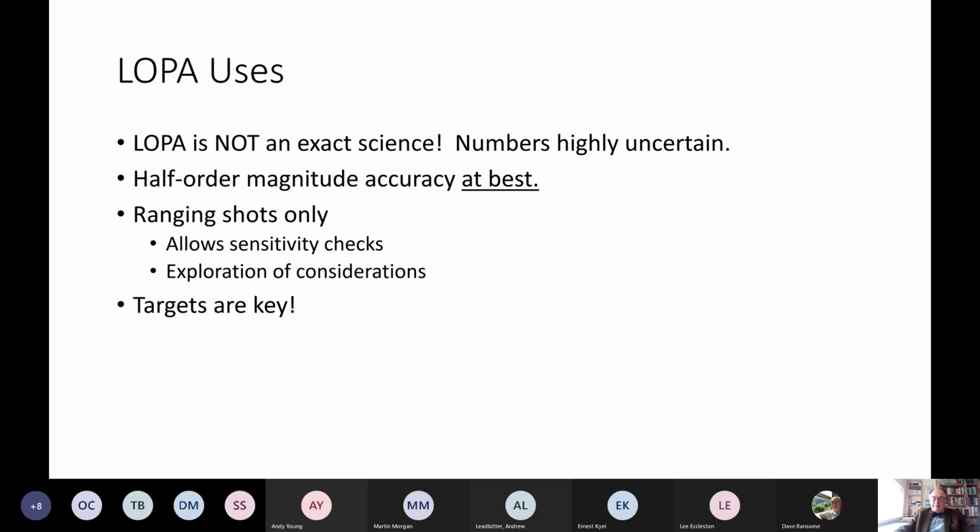The implication of the broadly acceptable threshold is that if you establish the risk is below that threshold, then you don't need to look at it further. It's not to say that the broadly acceptable threshold must be the target. And for most process hazards, certainly, a target at 10 to the minus 6 would typically be well beyond the ALARP consideration. Not going to explore that in detail, but at least I've alerted you to that possible confusion, possible difficulty there.